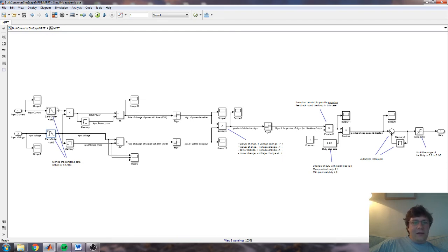sort of, I wouldn't say replicate, that's being a bit nice, are the most primitive expression of what an ADC does that you might want to put into a simulation. This is not an ideal setup we've got here, it's just an example. One of the major problems with it, in fact, is the stability of the feedback loop that we're creating is deeply bound up with your sampling times and how long it takes you to do your calculations.